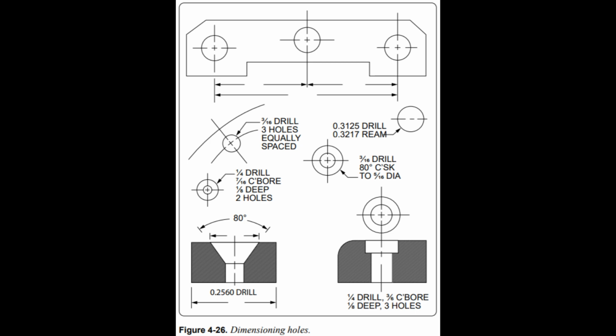Extension lines. Extension lines are used to extend the line showing the side or edge of a figure for placing a dimension to that side or edge. They are very narrow and have a short break where they extend from the object and extend a short distance past the arrow of the dimensioning line.